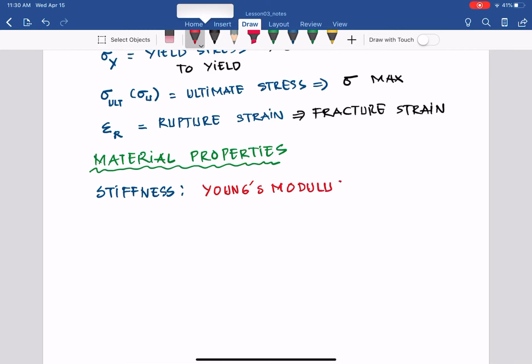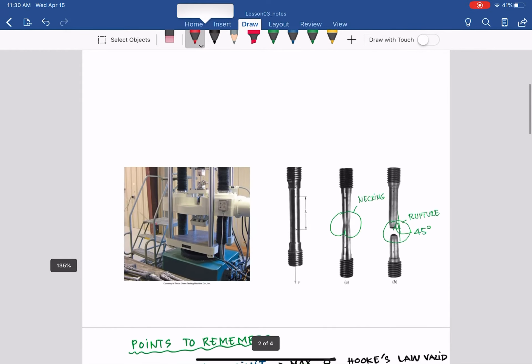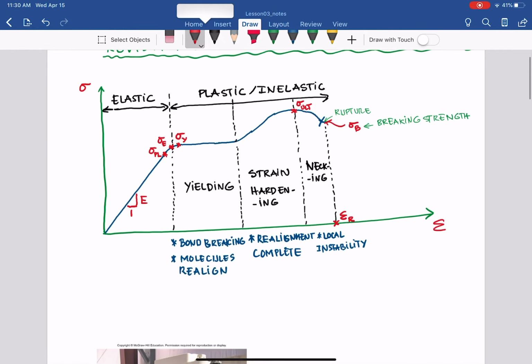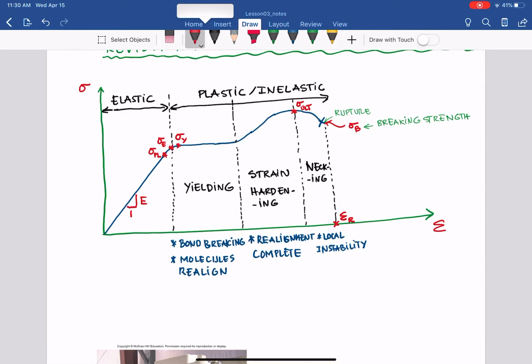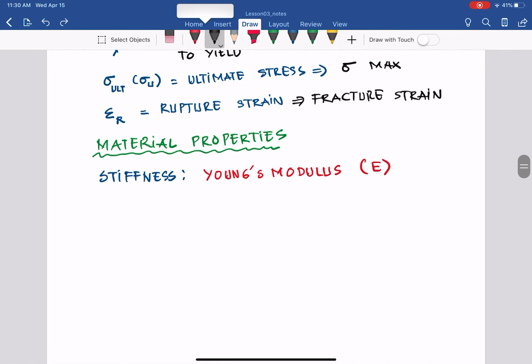Or modulus of elasticity, E capital, Young modulus. So between the two materials, if another material, which I just put in green here, has a curve above the blue curve, then the material in the green curve has higher E, it means it's stiffer. So stiffness: that material we call stiffer. So we measure the stiffness of the material using the Young modulus.